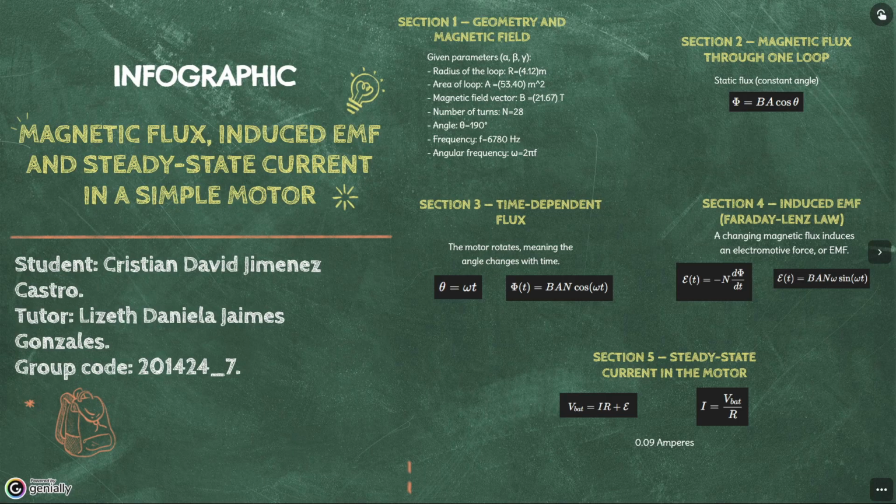In conclusion, we calculated the geometry of the loop and the magnetic field. We obtained the magnetic flux for a constant angle and for a rotating loop. We used the Faraday-Lenz law to find the induced EMF, and finally, we determined the steady-state current using Ohm's law. This analysis illustrates the fundamental principles behind how a simple motor generates and responds to magnetic induction.